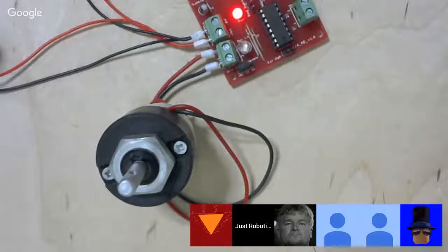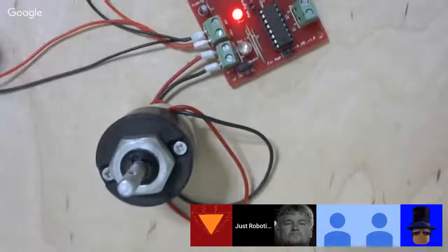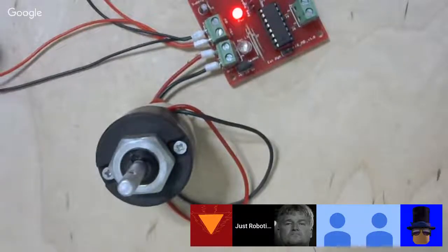So this is actually PWM, but it's not as easy as saying we do it with switches, because the switches that we use at home or in household appliances are not meant to be turned on and off at that high frequency. They might just end up getting spoiled. So what we do is write a program in Arduino to turn this particular motor on and off at a particular rate, so that my motor speed will eventually vary.